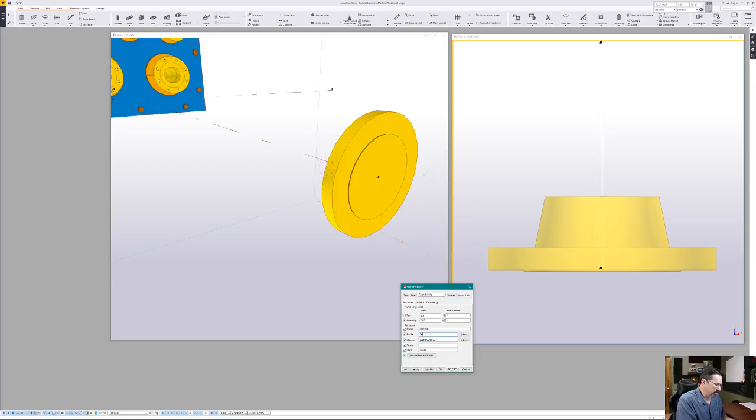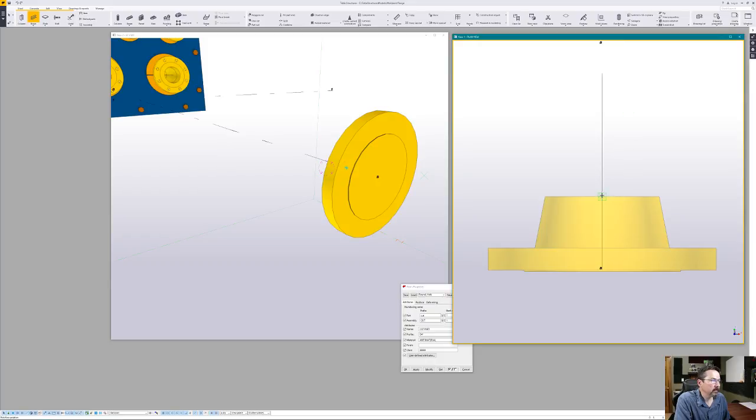And then to make sure that it did it right, 4.026 inches, and then we'll hit apply. And then we're going to pick up our beam command, and I'm going to draw this piece. I'm going to give a control point right at the middle of this, and I do this by holding down the control key and giving a point. What that does is, it looks like I've given an actual point, but I haven't. It's called a control point, and it's waiting for the actual first input point.